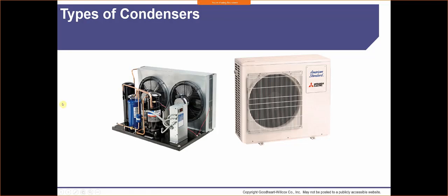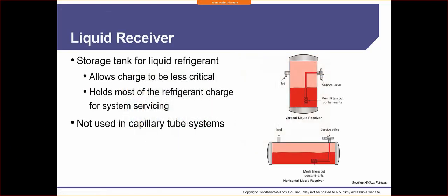I can put an accumulator in here, or a storage tank, or a liquid receiver, and all that refrigerant is just going to come inside here. It's going to collect in this reservoir, and then it's just going to come out as needed. So it's really nice to have. It prevents liquid refrigerant from overloading the system.